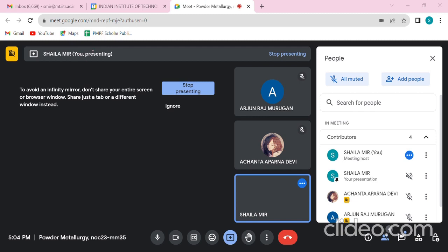As you are decreasing the pores, you are increasing the density of the material. Grain coarsening is also associated with the pores, because as you go to a higher sintering temperature, grain growth takes place, and the pores present along the grain boundaries try to break away from the grain boundary. The pores are separated from the grain boundaries.